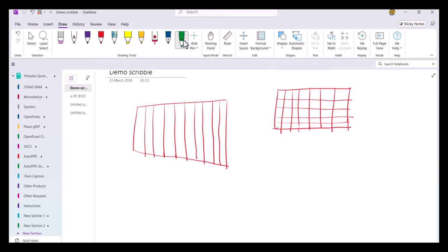If I want to show the local axis orientation of every plate element, I'm showing it by L. L means one of them would be X and the other would be Y axis. So any one would be X or the other would be Y. So these are all oriented in very well organized directions, essentially along the edges of this rectangle.